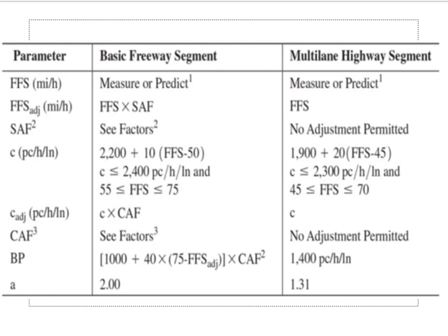Whenever you plot the graph, you need free flow speed and capacity. Before you start using these values for the graph, you have to see if you need any adjustment or can use these values as they are, or should you apply any adjustment factor?